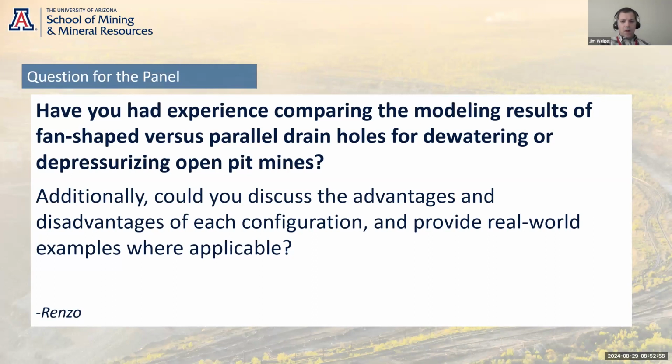But I think Travis also hit on this, we have 2 rigs that are currently running in Bingham Pit as we come down the wall, and we do fans, and we can get more drains in by fanning out, having one drill pad, because for us we have to have drill pads that are isolated from all our haul traffic. So you can imagine trying to build one of those up every 100 feet down the wall on the active cut, versus putting in one, and now you're able to just do one every 300 or so feet because your fans are going out into the formations.